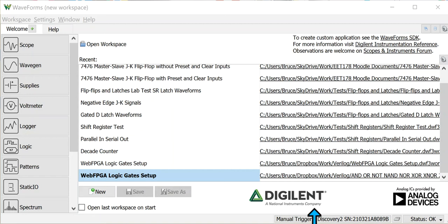First off, a pattern generator could be compared to something a little more known, like a signal generator in the analog world. In the analog world, sometimes you want to create signals like sine waves, sawtooth waves, and square waves, and you want to adjust them any way possible, center them on 0 volts, or have them go from 0 to 8 volts or 0 to 12 volts. You would use a signal generator for that. They're usually limited to 1 or 2 channels, and it's a standard piece of test equipment that you find on a workbench.